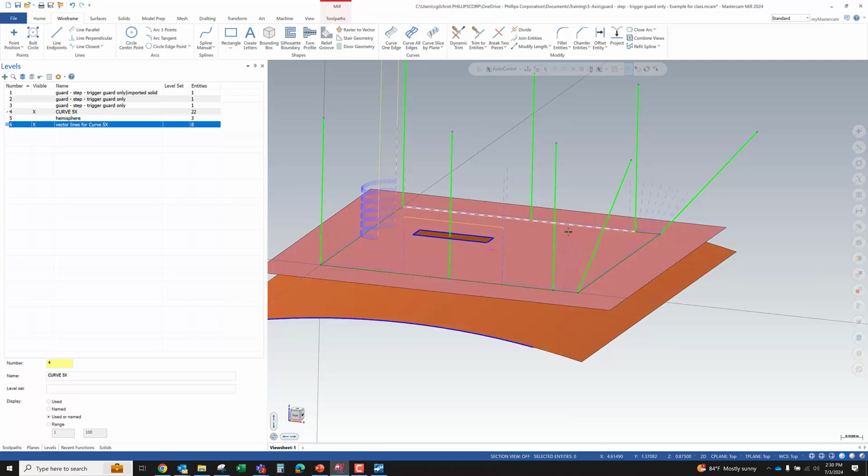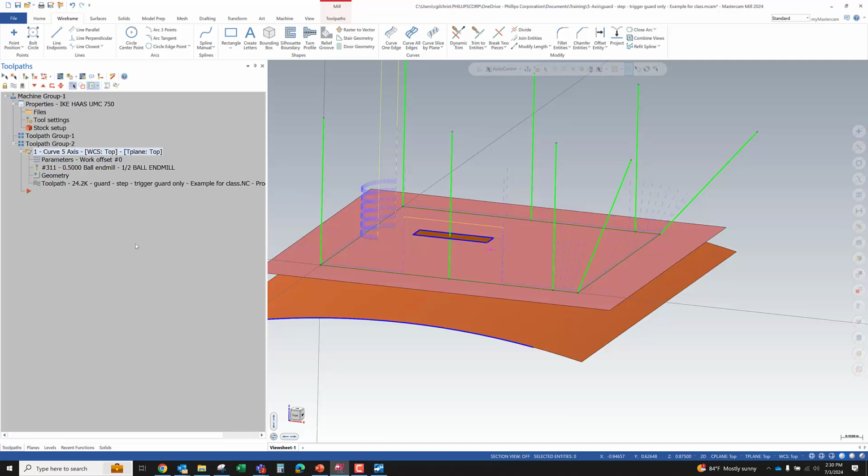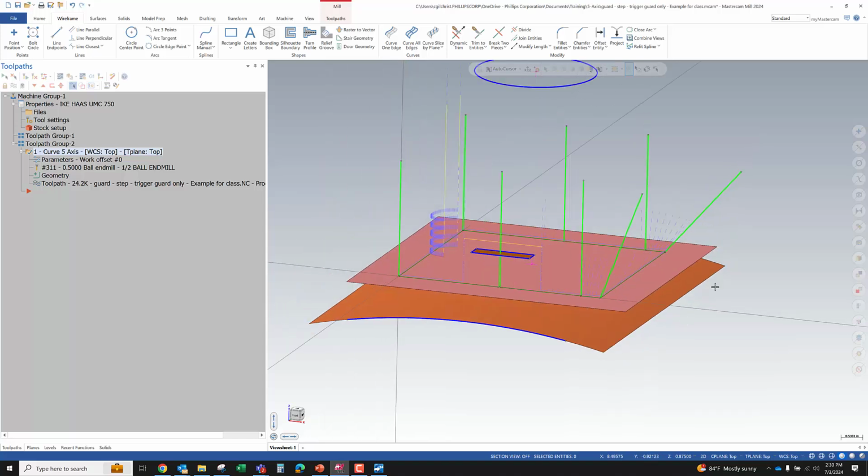There's all kinds of reasons that you could be getting jitter in the toolpath, but I think the secret is just going through here systematically and using different controls and realizing that the inputs to the toolpath are geometric and numeric, right? You're going to select geometry and you're going to type in data, and sometimes changing a number by a tiny fraction, there's some weird rounding thing inside the algorithm, and that cures it.